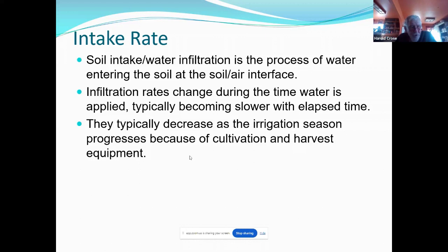So if that grower tells you, yes, I'm plowing that field, then after that event, after they've planted the crop, I'd take them out in the field with an auger and drill down until I hit that hard pan and find out what level it's at. Because that's going to be a restrictive layer, not only for water penetration, but root penetration.